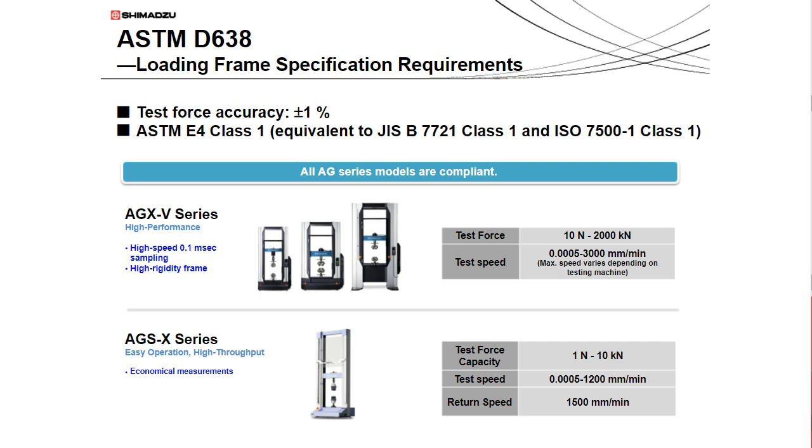And you also want to confirm that the test forces are within the calibrated range of the load cell. Many test frame suppliers provide load cell calibration services so that you can confirm that the values that you're reading in test force are within the accuracy requirements.